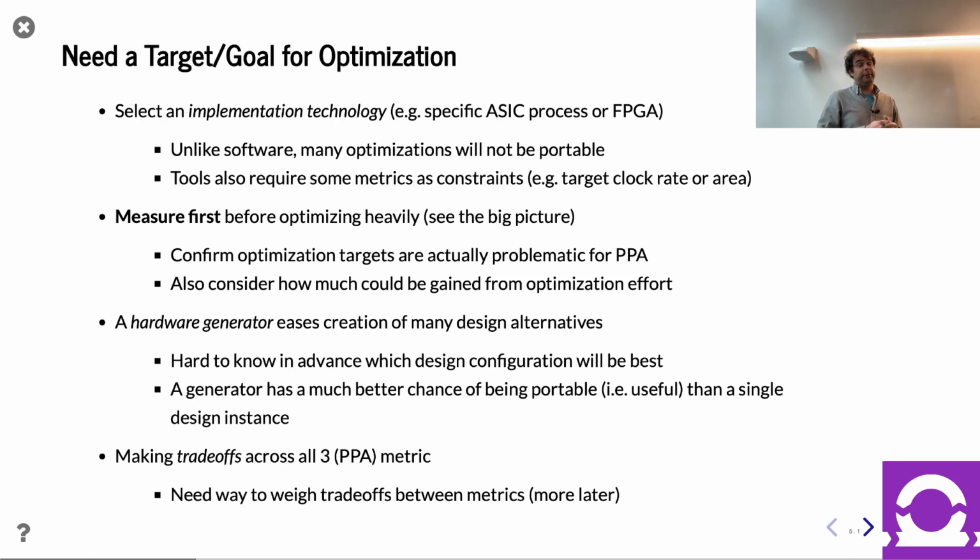So you're saying who chooses the implementation technology? That's usually a choice way above your pay grade, so to speak, right? Like I said, there's usually some small choices you can make. Which foundry you're working with, if you're doing an ASIC, is a big thing. It's not just a small one-off choice. It's a big decision, right? And even with a given foundry, which technology you're using is also a big decision. Even for a given technology node, there might be subtle variations, like the high or low voltage process, high VT, low VT or multi VT, whatever. There are some knobs there.